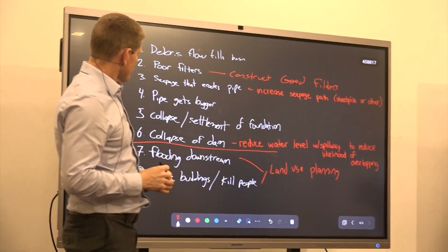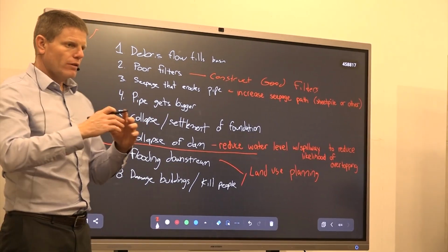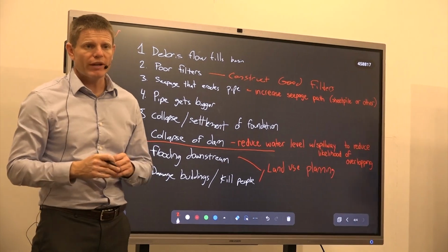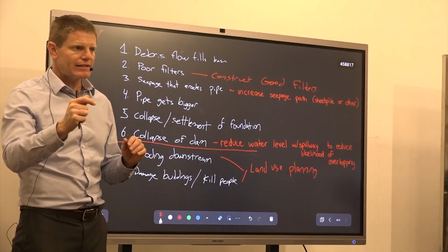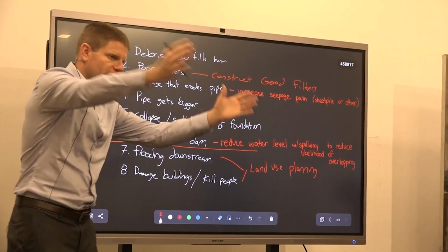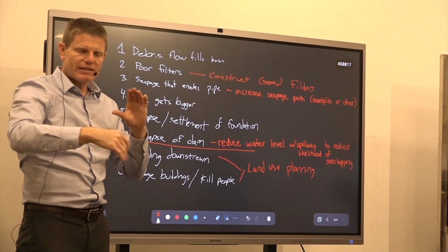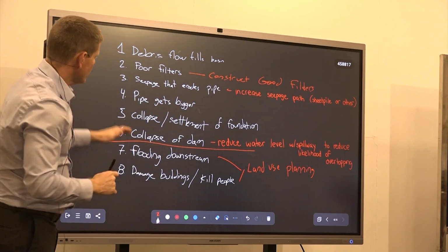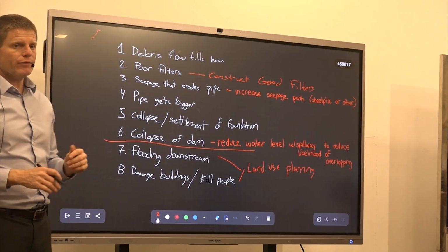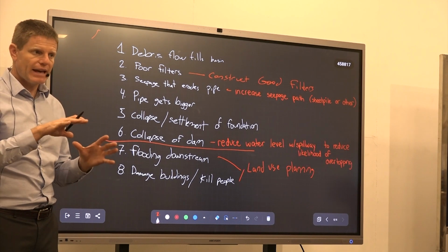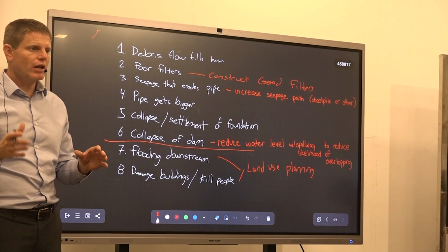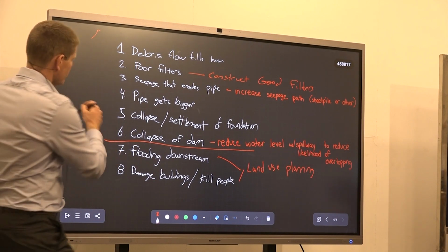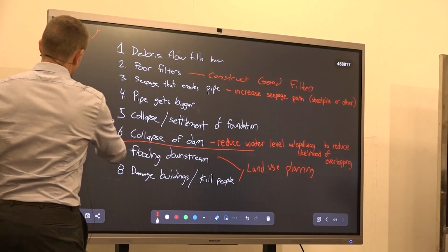Yes, so the pipe begins, right? It takes time for this to develop. And that's an important point, that it doesn't happen instantaneously. It's not like a debris flow hits it and it collapses. It's a process that begins and the pipe gets bigger and bigger and bigger. And so in some cases, you could have equipment and materials staged downstream of the structure that can respond in case the pipe begins.